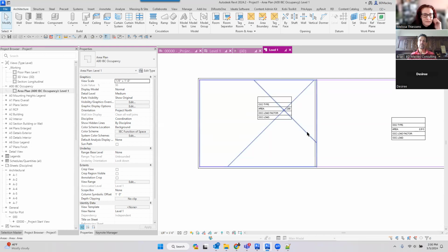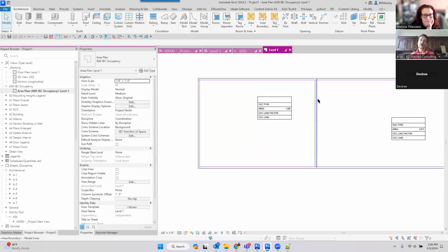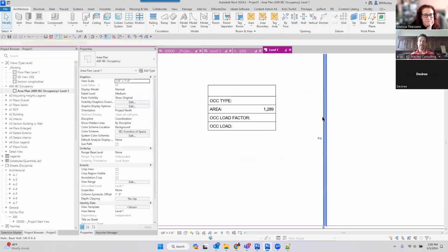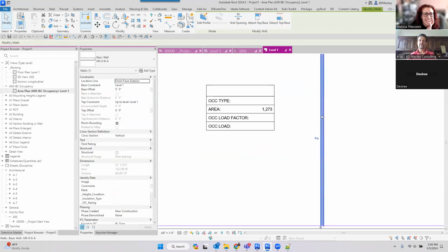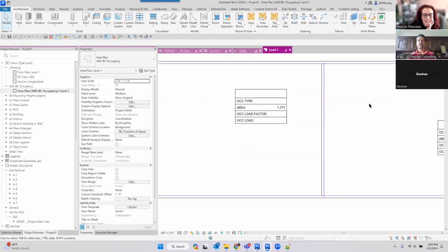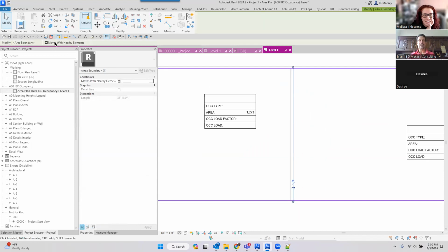Yeah, right. They're also not phaseable, just like rooms. Check the "move with nearby elements" option, and it'll then move with the room or with the wall. Yeah, that command scares me. I've used that before, and then I've moved a cabinet, and all of a sudden walls start moving with a cabinet or other things. So I can honestly say I almost never use this command.